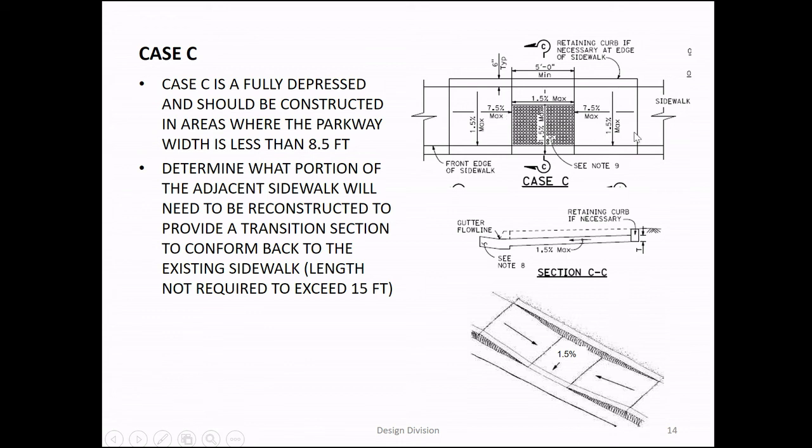Caltrans is 50 inches. ADA is different. ADA is 4 feet. But what's existing? Because you're building this new, you have to build the 50, Caltrans 50. If you don't have the space, you can deviate from there, as long as you have the 4. ADA allows you 36 minimum. Do I have to do like an exception, and you need a detail or something?